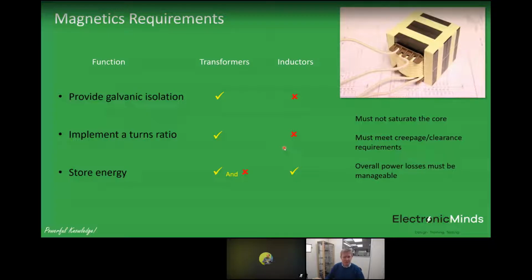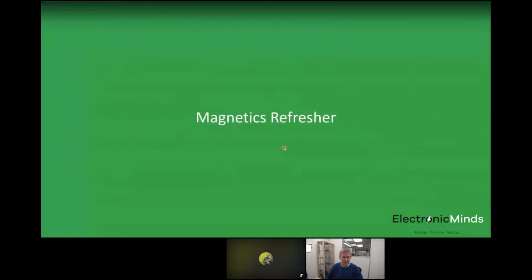And you've got to manage power losses. So in this webinar, I'm also going to describe some of the main loss mechanisms that you'll experience in magnetic components and how you can design and quantify those. Other parasitics come in as well. Whenever you've got physical windings, you can have leakage inductances and capacitance between windings, and there are different techniques to help you trade off those parameters as well. Low capacitance is normally a good thing for high switching frequency.